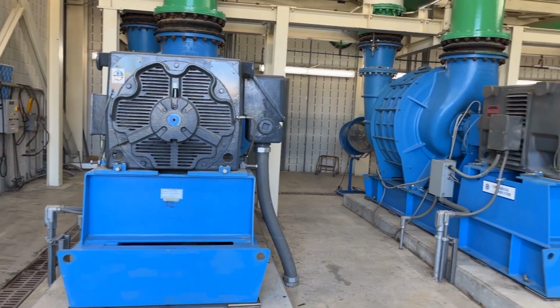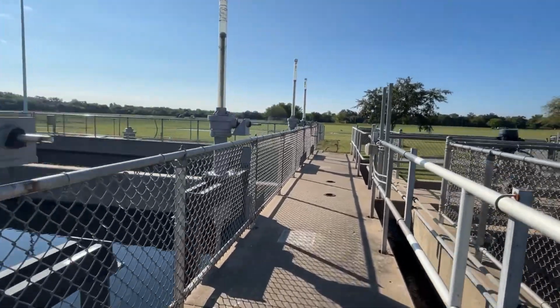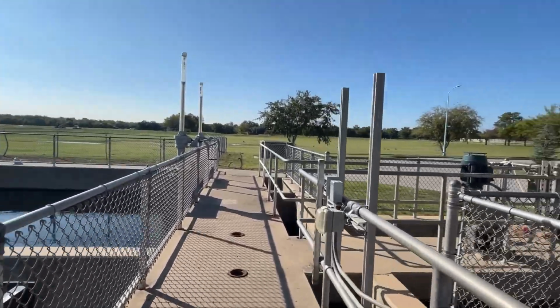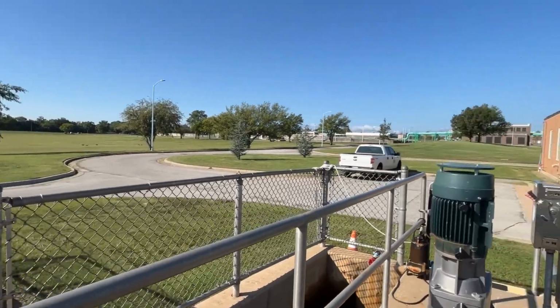Having that extra set of eyes to watch our equipment, I believe they do 3-hour increment samplings, is definitely very beneficial to us. So every 3 hours, that's a lot of vibration data coming in. It is. Most places I go to, they'll run a route maybe once a month.